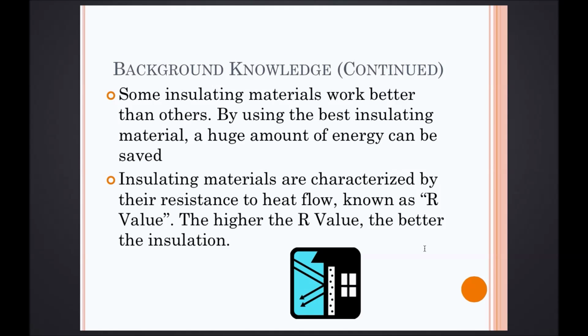Some insulation materials work better than others. By using the best insulation material, a huge amount of energy can be saved for the household. Insulating materials are characterized by their resistance to heat flow, known as the R value. The higher the R value, the better the insulation.